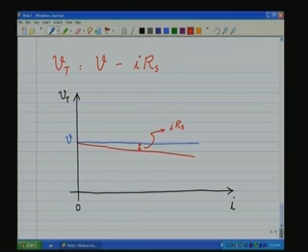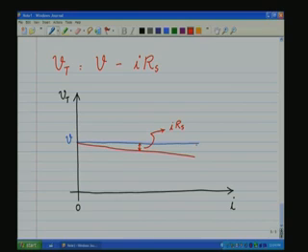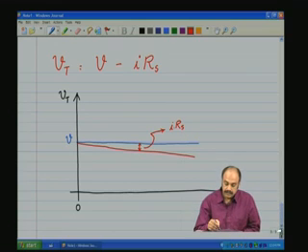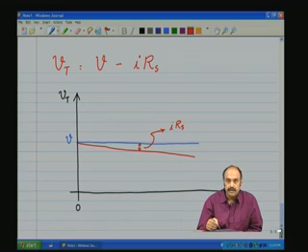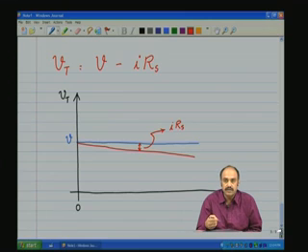Therefore, the goodness of a voltage source can be quantitatively measured by looking at the VI characteristic. The more horizontal the VI characteristic, the better the source. Which means the more horizontal it is, the I Rs drop is small, and therefore Rs is small, and therefore it is a better source compared to one which has a much higher droop.